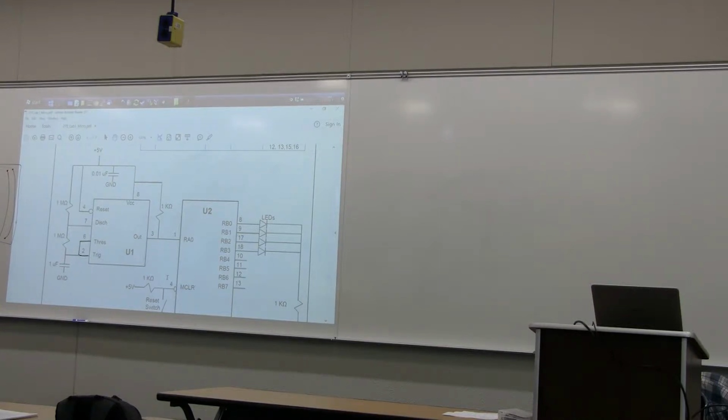Pin 2 needs to go through your capacitor to ground. So this is the big orange-yellow capacitor. Pop into a hole here, go into that capacitor, and plug the other end into ground. And you can do that without any wires, right? There are two big long leads on that capacitor. So just take one of them, pop it in the same row as pin 2, pop the other one into that blue rail. Now you've got this connection.